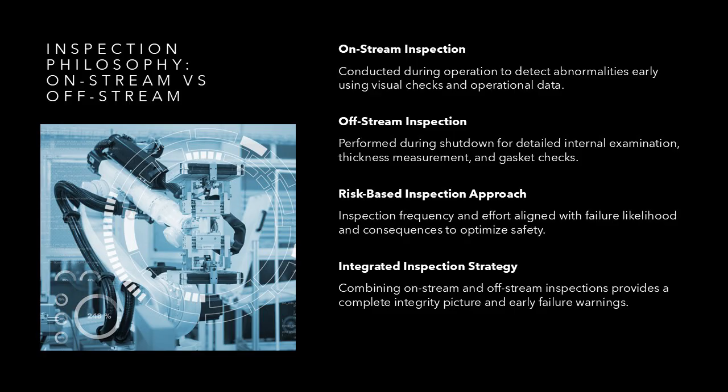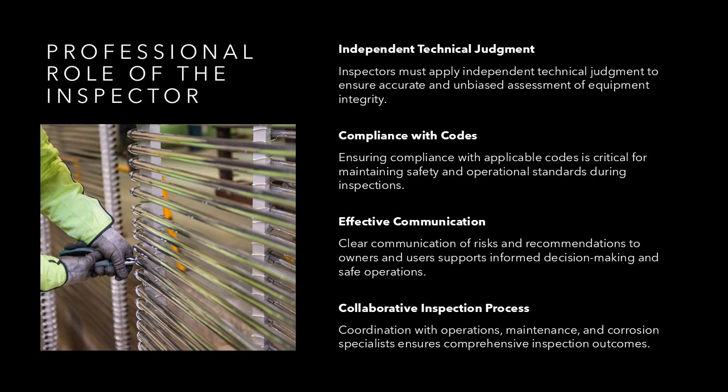A risk-based approach is encouraged, where inspection effort and frequency are aligned with the likelihood and consequence of failure. Inspectors should integrate both approaches to form a complete integrity picture, recognizing that many PHE failures provide early warning signs if properly monitored. This final slide emphasizes the professional role and accountability of the inspector in managing PHE integrity.